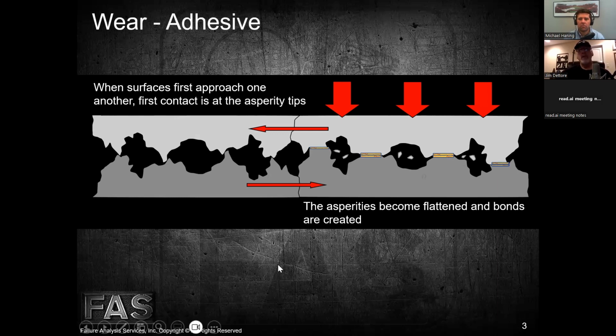When we see adhesive wear occurring, sometimes it causes failure, sometimes it's catastrophic. Other times it is a very small point where it's created an issue, but then either the load has been released or sufficient lubricant has been supplied to keep the surfaces either lubricated or cooled. And sometimes we'll just see small areas that have some adhesive or wiping damage, but it didn't lead to catastrophic failure.